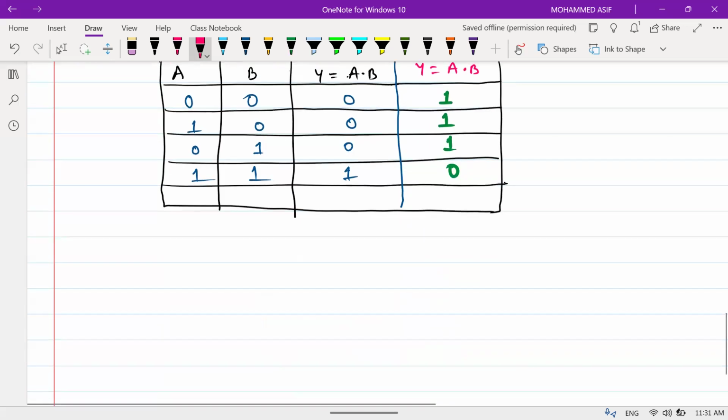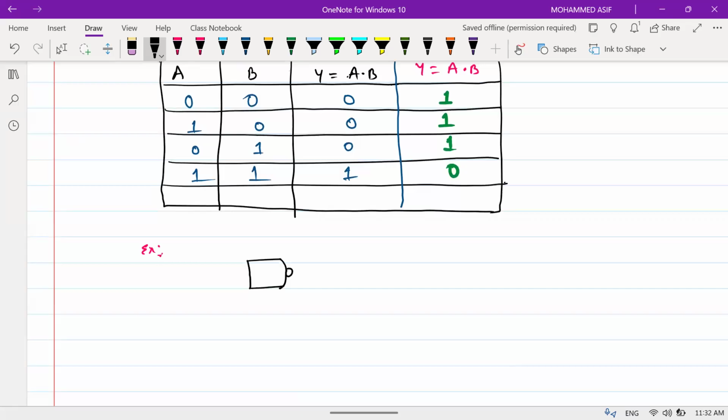Look at this example. For the NAND gate, if our input is like this, the NAND gate symbol, if I'm taking it right. Now here, if this is your NAND gate and this is your output, if I'm giving two inputs the same, say for example this is A, Y value will be equal to how much, beta? A bar. Y is equal to A bar, and which gate is it, beta? NOT gate.